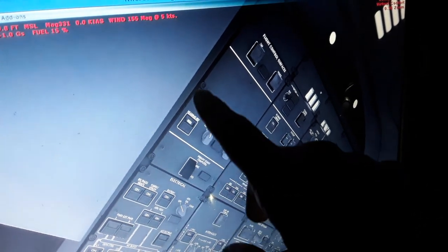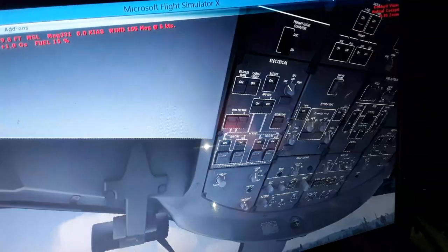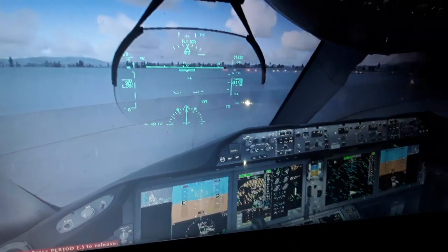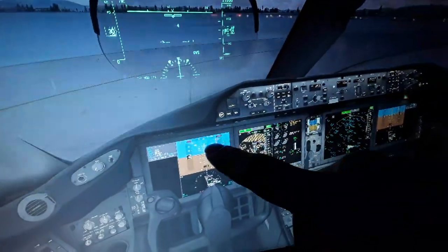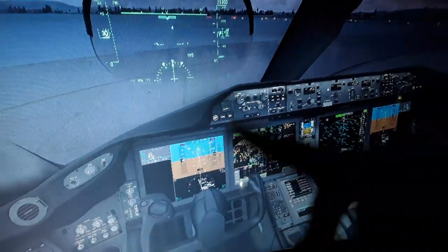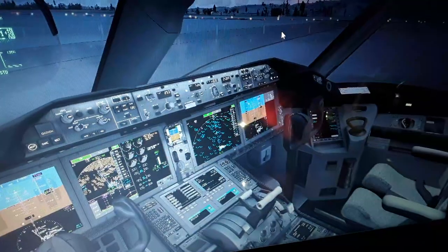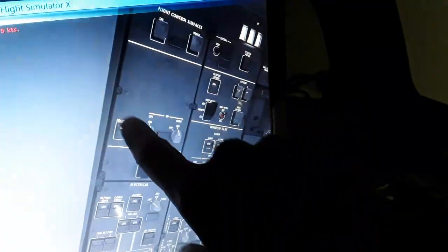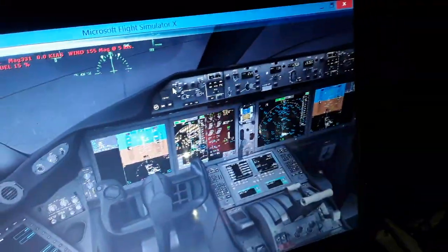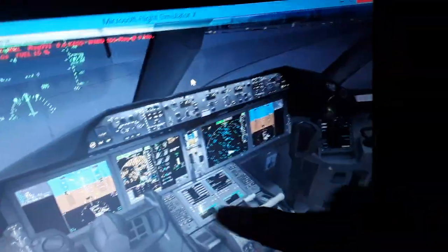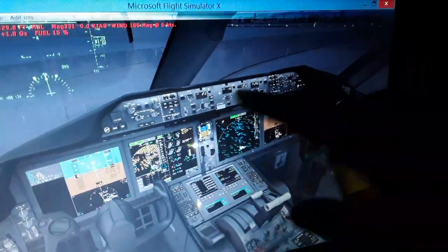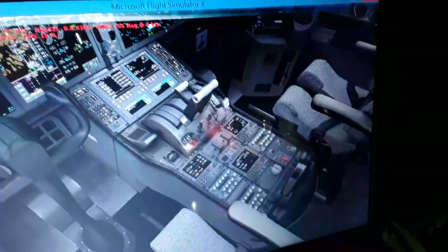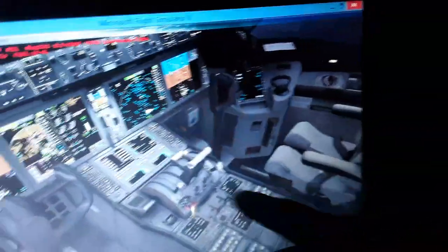The angle of attack of the aircraft as it flies. So the airspeed, altitude change using barometric, pitot static and pitot dynamic, the angle of attack, radio altitude. So this compares all the information. Also the GPS receivers, we have 3 GPS receivers over here in this section. This is the air data computer of the aircraft. So the air data navigation is supplied to all systems, also flight management computer, autopilot, flight director system panel, all the throttle. So we have the thrust levers.